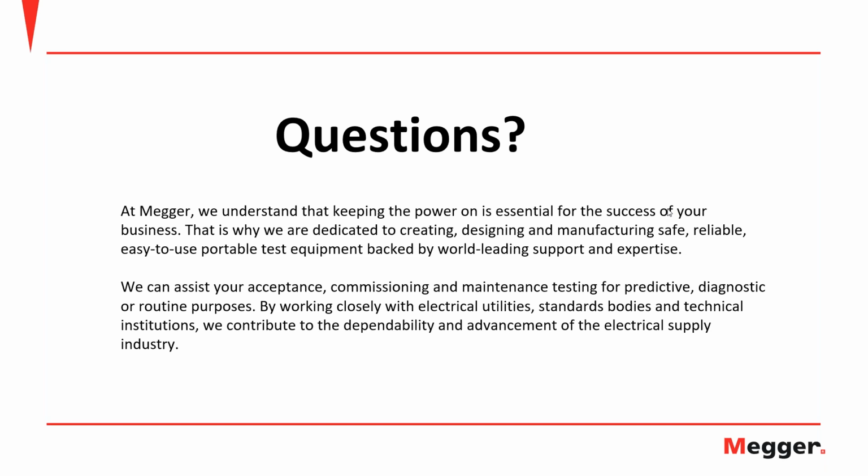Yeah, I've just pulled up the ASTM D1816 standard, and it says for a 1 millimeter gap setting, the range must be less than 120% of the mean of 5 breakdown voltages. And then for a 2 millimeter gap setting, the range must be less than 92% of the mean of 5 breakdown voltages. So I think it's clearly stated in the standard what the actual criteria is. And the range is obviously the highest value minus the lowest value. Yes.